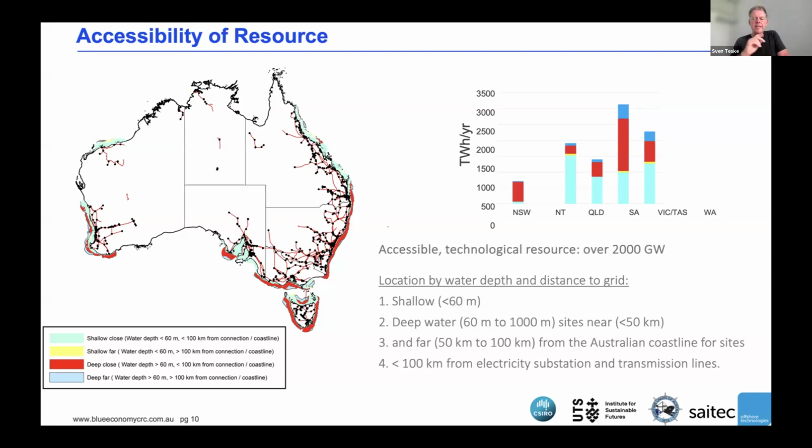There is one other additional requirement, and that is the port facilities. You need tugboats, you need suppliers, you need a number of vehicles and infrastructure to supply and maintain and build in the first place offshore wind farms. Therefore, you need quite a deep harbor. A shallow harbor wouldn't be suitable. So we're talking about 10, 15 meter water depth. That would be the preferable port. And then you reduce the locations even further, as Australia has more than 15,000 kilometers of coastline, but not too many deep water harbors. So again, you end up where the current coal industry and oil and gas industry is located.